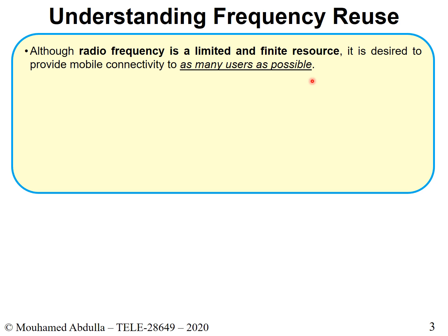There was also another approach of multiple access scheme known as TDMA, time division multiple access. In time division multiple access, you had the entire frequency. The only difference is that the time when you can send your signal was chopped, right? So in certain time slots, you can send your signal. It's kind of similar to what we saw earlier with TDD. That was used also in 2G in addition to FDMA.